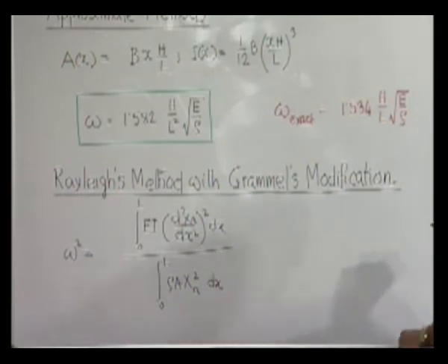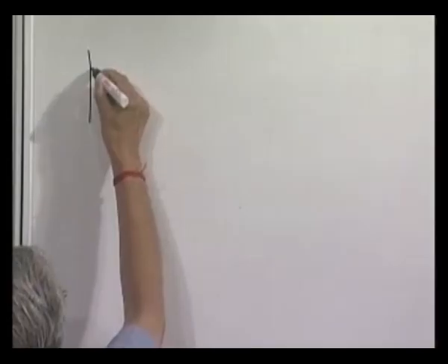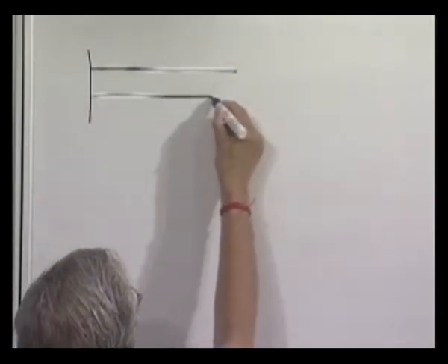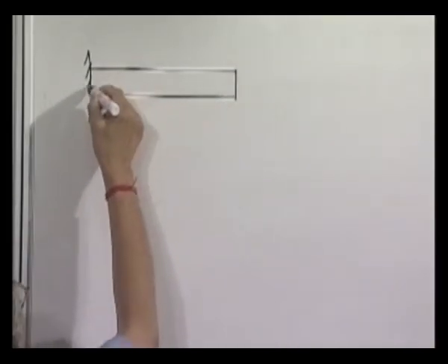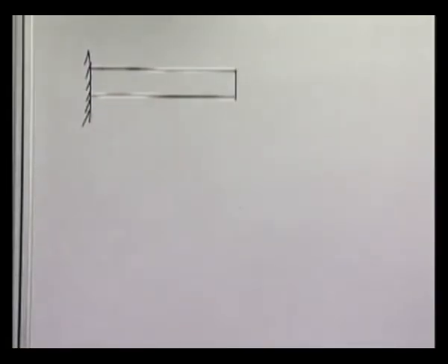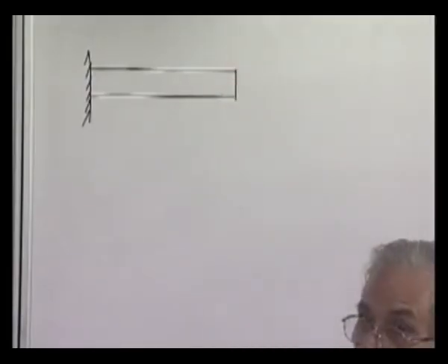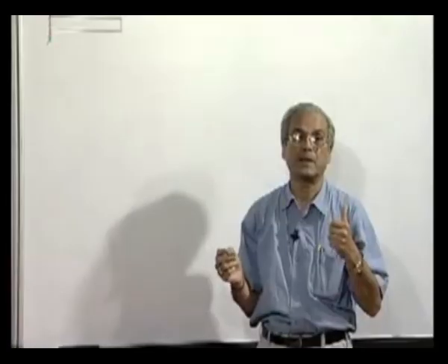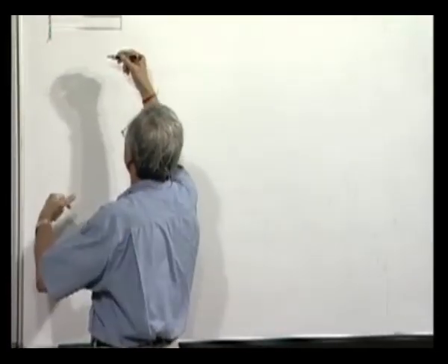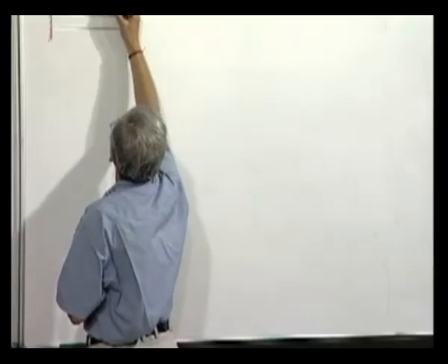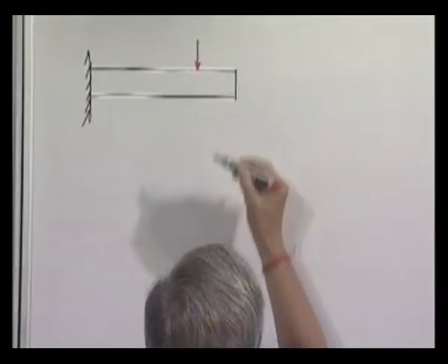Say for example, if we take any kind of beam, but we will take an example like a cantilever. So what will be the inertia force acting? Inertia force acting on any particular element will be the mass of the element into the acceleration of the element at the peak point, that is peak acceleration, with a minus sign. So it can be either in that direction or in this direction, so it will be something like this, inertial loading.